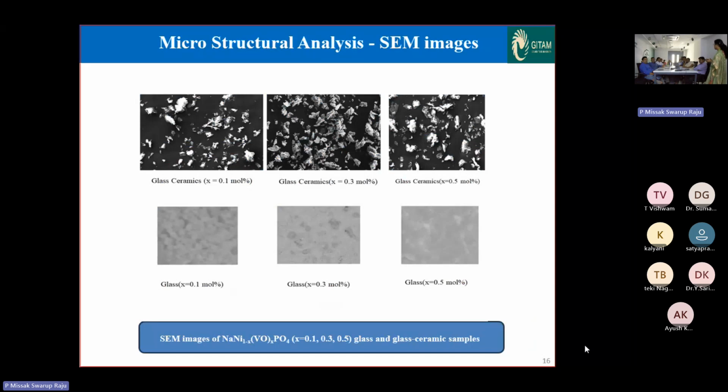Sir, what is the difference between crystallite size and particle? The particle is some lower value compared to the crystallite value. So that's why I took the microstructure value for the calculation of the particle size. No. Crystal means a group of atoms, and particles mean a group of crystals. So definitely there is a change. If your particle size is exactly the same as the crystal, then we can call both the same.